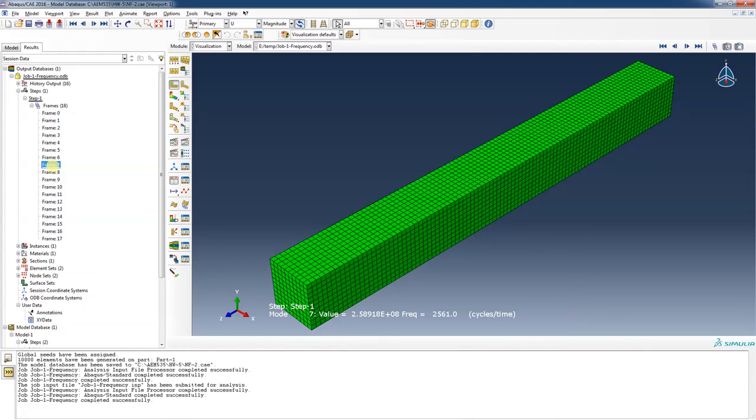So we got a little difference in that finite element calculated natural frequency. Now it's still not super close to 2653. Let's go ahead and calculate the percent error while we're here. 2653, 2561. It was about 3%.